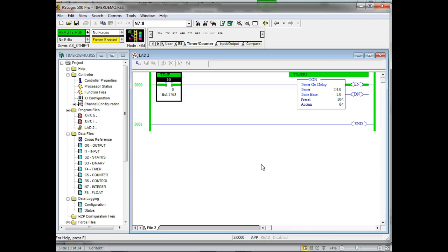Yeah, well, we'll do that right now. So here it comes. Now notice, enable still true, everything stops, and then the done coil went true. Okay, that makes sense? Well, the timer itself is energized. It's just that the done doesn't energize until it's done. Okay.